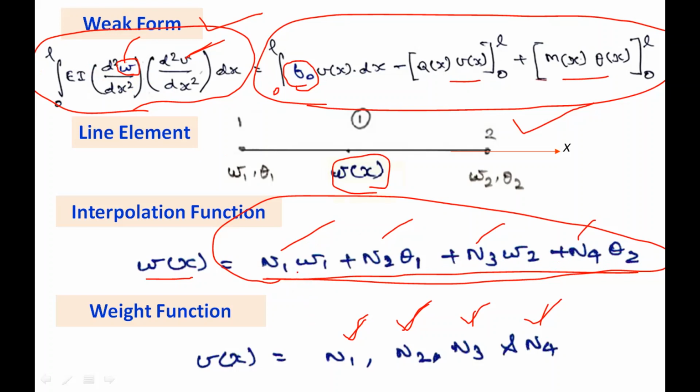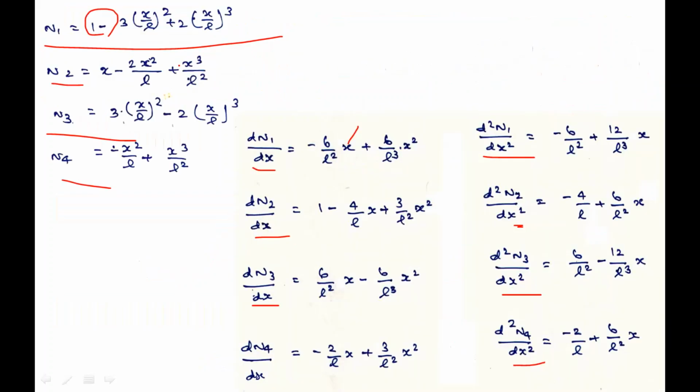When you expand this one, you get 4 integral parts. One equation gives 4 elements, that is the elements of a row. So I will explain how an element of the stiffness matrix is derived. Take only one element. Similarly, in the force matrix also, we will see the right hand side force matrix. We will see how the elements of the force matrix are derived for only one element. This is going to be written as Kij, which is going to be the stiffness matrix.